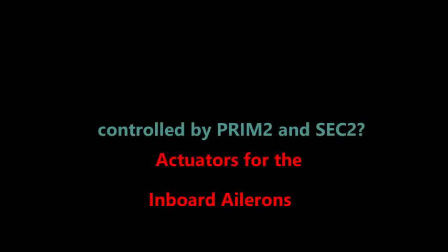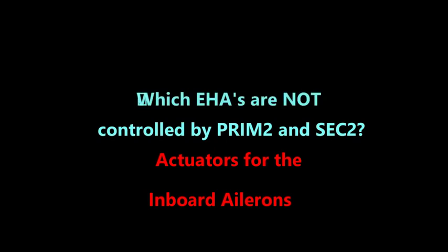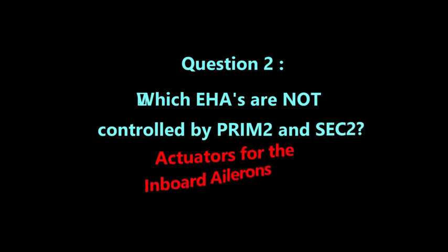Which electrohydrostatic actuators are not controlled by the PRIM2 and SEC2? Okay, is it the actuators for the inboard ailerons or the actuators for the rudder? That's going to be the actuators for the inboard ailerons. Those are not controlled by PRIM2 and SEC2. And there's a diagram that shows all that that we have for you.